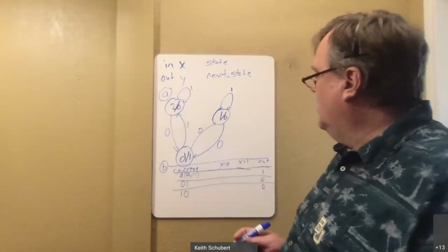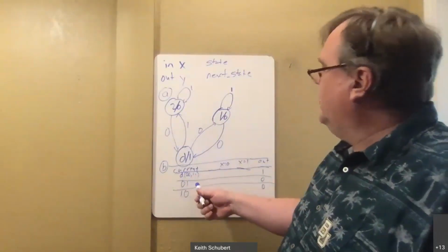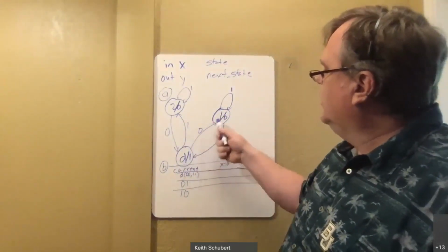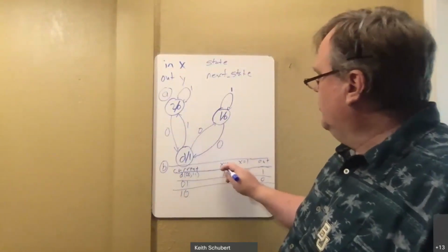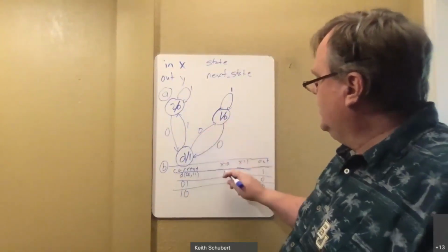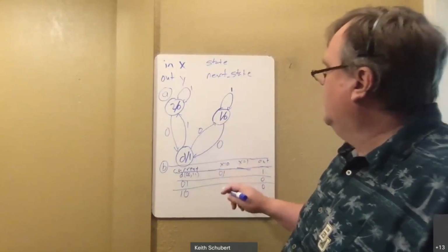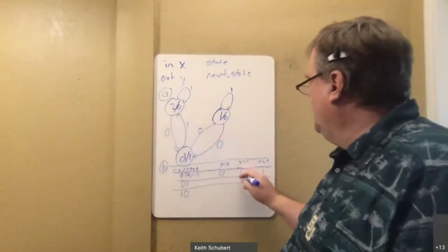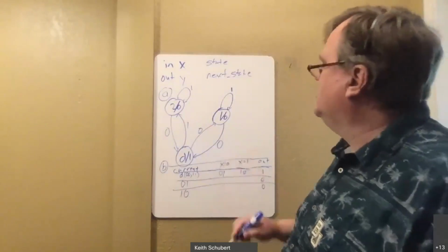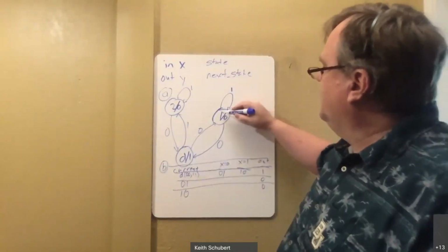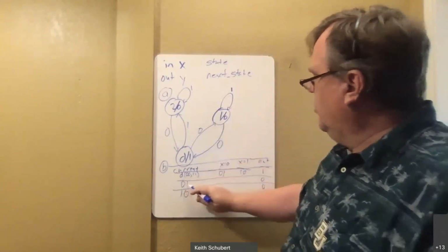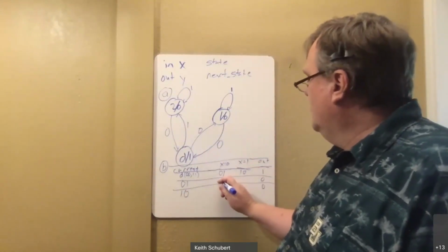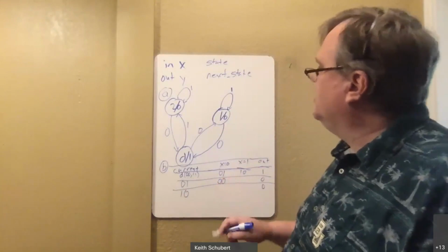Nice and easy. I can go to default and look at where its 2 arrows go. At default, the arrow that goes away from it that's labeled 0 goes to state 1. So if the input is 0, the next state will be 1. If the input is a 1, that's this arrow, its next state will be 2. Easy enough. If my current state is 1, which is 0, 1, on a 0, it goes back to my default case, in particular 0, 0.